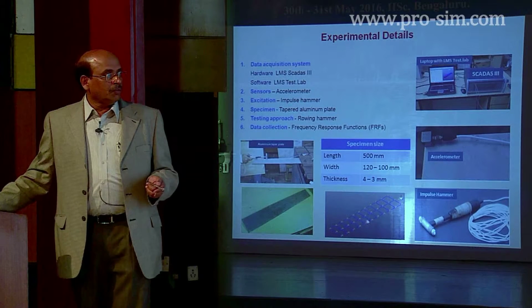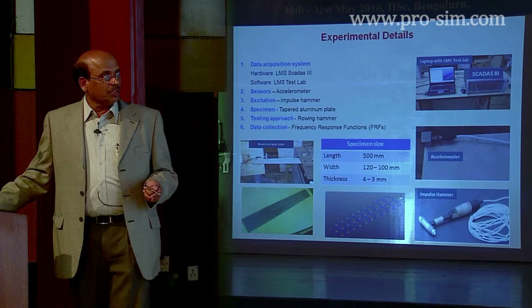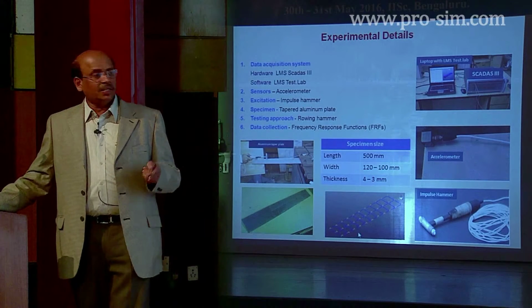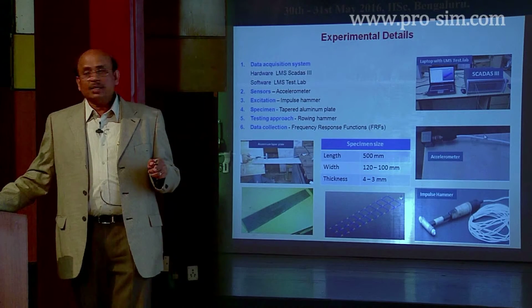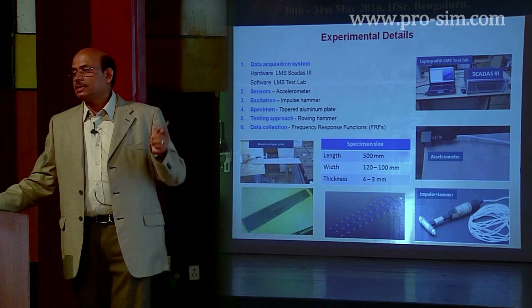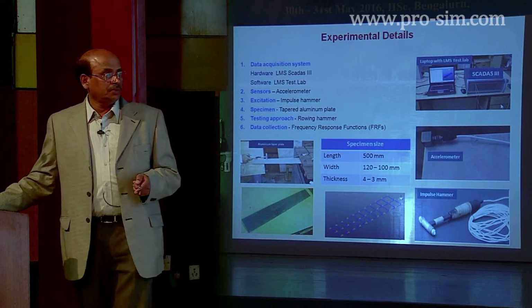Whatever grid we use for capturing the vibration characteristics, the same grid we use for the finite element model also. Then we get some eigenvalues and eigenvectors for that. That will be replaced with whatever we obtain from the test. Then we get a finite element model which actually mimics the actual structural behavior. On that, we do all other studies.